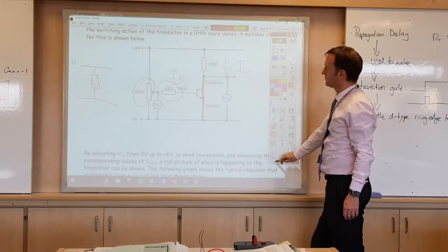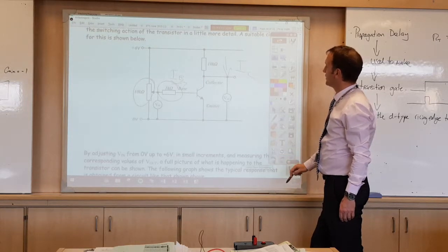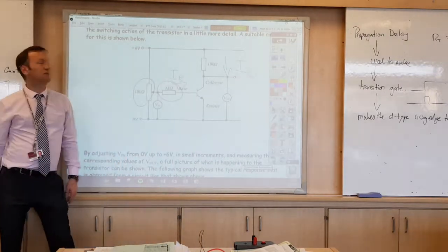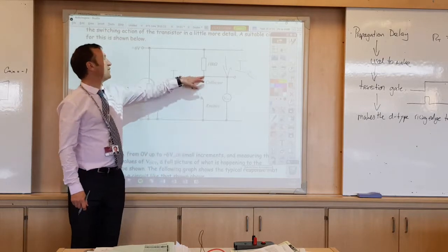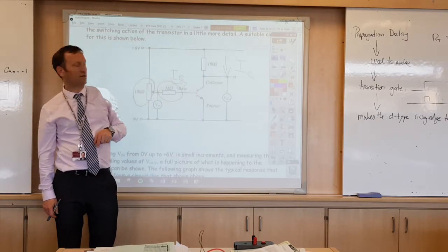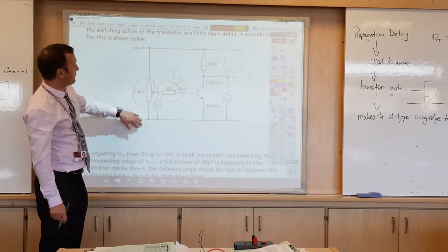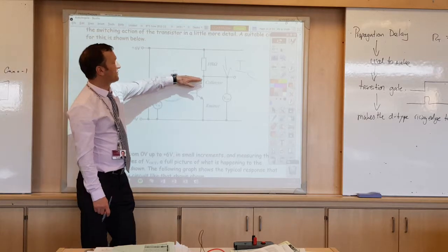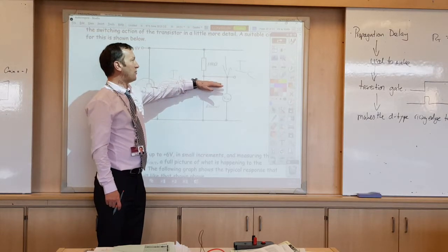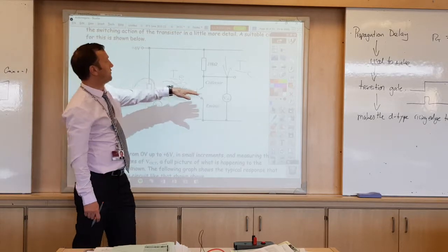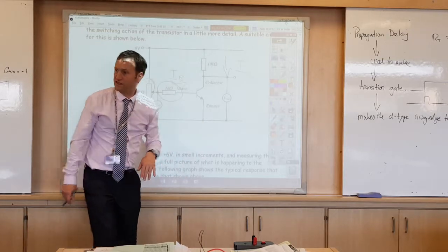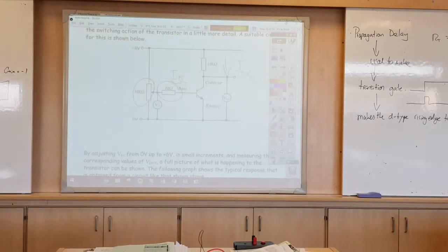So, okay. So when the transistor is fully on, actually the voltage across it will be 0. When the transistor is fully off, then the voltage across it will be 6 volts. So what's going to happen is, if we start building up the voltage slowly going into there, then it'll start off with a high voltage here, and it'll drop. And eventually, if it drops to half the supply voltage, then half of the voltage is across the resistor, and half the voltage is across the transistor. And it'll be like this is when it's in its half on, half off state.